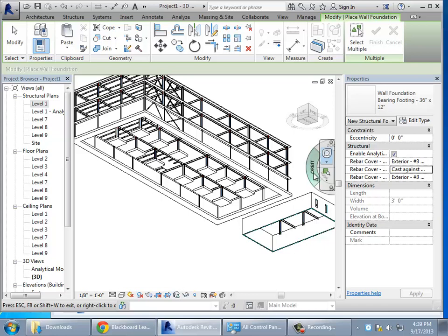The fact that all those little roof purlins, those rafter-like things, are spaced every 2 feet or 60 inches, whatever it is, gives you a clue that it's probably a beam system. It probably is some very regular spacing. You're choosing some sort of profile, putting them at a very regular spacing. So beam systems in general work pretty well. The only variation you have to worry about is sloping, as opposed to being perfectly flat. You might say, well, gee, how do I do that?